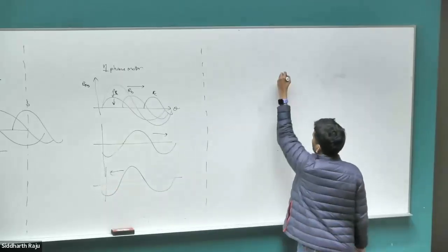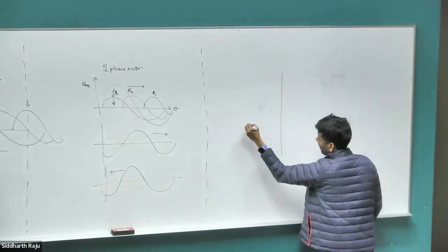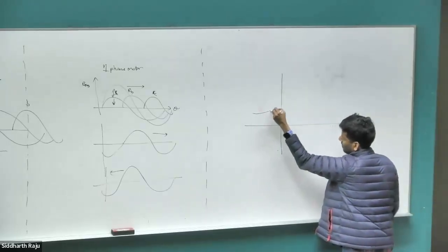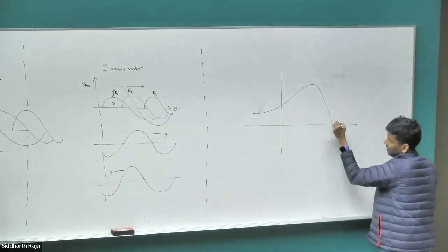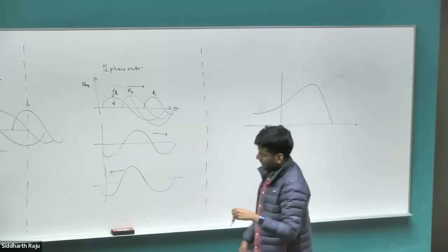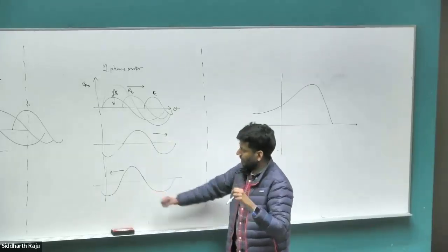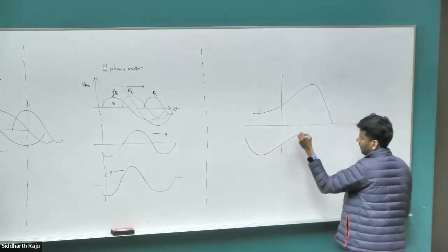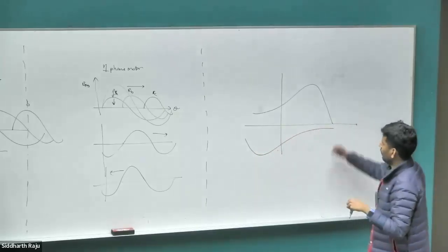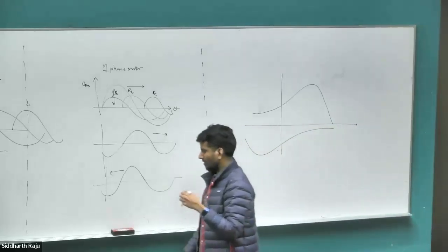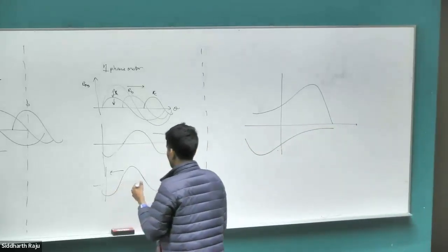So the three-phase motor that is traveling in the forward direction in our equivalent model will create a torque that looks like this, which we have already derived on the graph on the left there. Now the torque that's generated by the reverse traveling wave would be the exact mirror image along the x equal to y axis. Right? Whatever this curve is, will be the exact opposite of this curve. So let's think about what's actually happening intuitively.